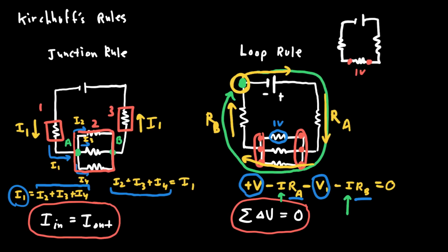I take the complicated circuit, I combine things that are in series and in parallel to find their equivalent resistance. I simplify the circuit as much as possible. Once it's simplified, I can probably find the total current in that circuit. Now that I know the total current, that's an added piece of information, I can build the circuit back up and look at the more complicated versions of my circuit diagrams to find new resistances, new voltages, things like that. So make sure that you have a plan for how you're going to attack circuits. We have Ohm's law available, we have the junction rule, the loop rule, and our knowledge of what's true about series and parallel circuits.